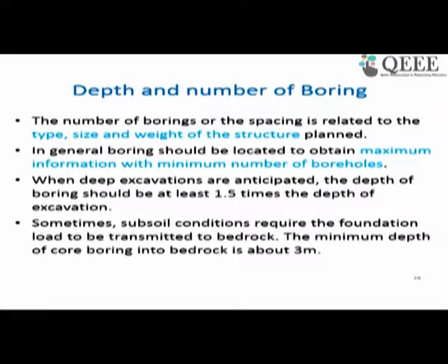Now, the most common investigation practices require some kind of boring. You might have seen various drilling operations at various sites. The first thing you have to decide about the investigation is how many boreholes, or drill holes, you should make. The next thing is what should be the depth of your borehole.